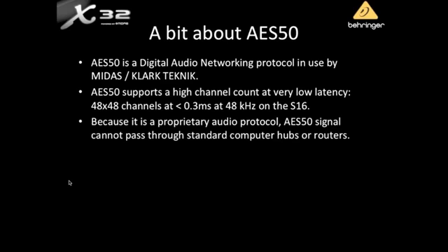Because it is a proprietary audio protocol, AES-50 signal cannot pass through standard computer hubs. Can't stress this one enough. It's an RJ45 jack, but it's not going to work with traditional computer hardware. It uses a totally different protocol, so don't do that. Maximum cable distance is 100 meters or 300 feet. So pretty much any front of house type position, you should be totally set on that.